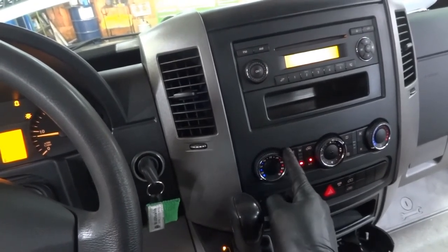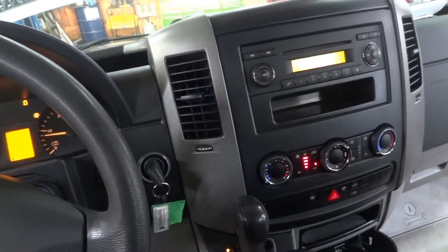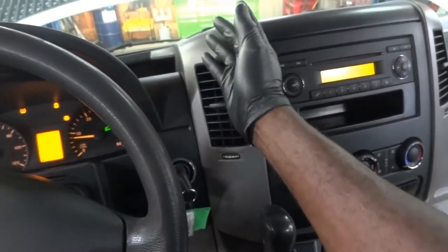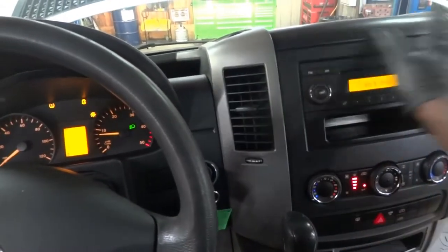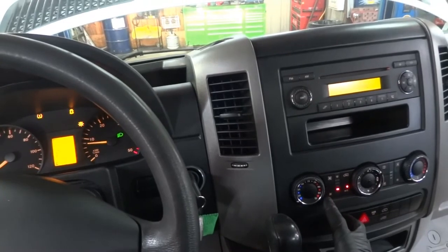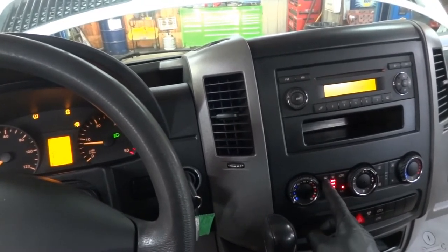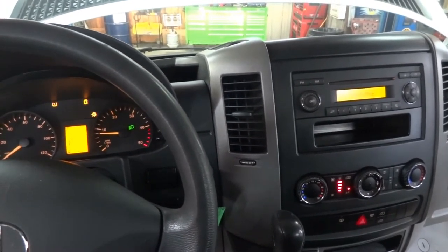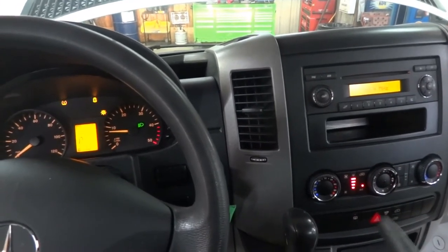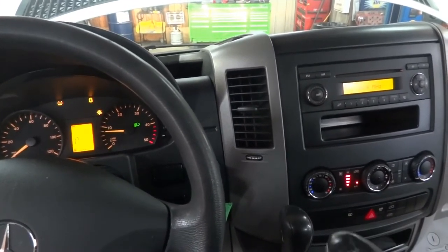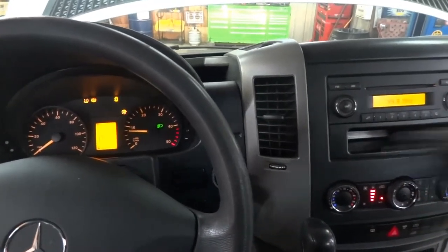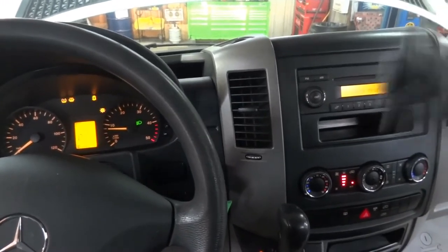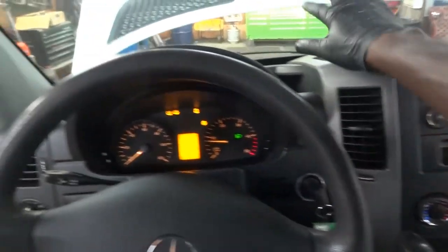So I am increasing the blower motor speed. Nothing. So it looks like our blower motor is not blowing any air out of these vents. And I think the customer was mistaken when he said the air conditioning is not working. I mean, it depends on how you look at it, but I believe the air conditioning is working in this car. The blower motor is not blowing any air through these vents, so there's no air being blown through the evaporator behind the dash. So that's why he said that the air conditioning is not working.